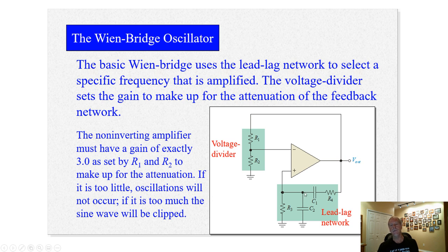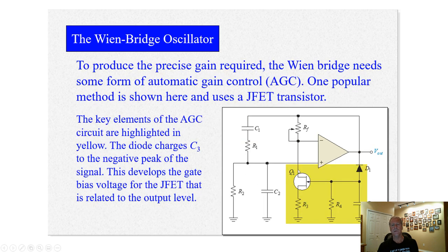Now, as I said before, a lot of times when you first start out, you have no signal, or it's very weak. So a lot of times we have to have a gain of greater than 1 initially. So here's a little circuit, a little field effect transistor, which produces an automatic gain control. If you see this, this FET has now replaced the lower resistor here. So you get a gain of greater than 1 when this is turned on initially.